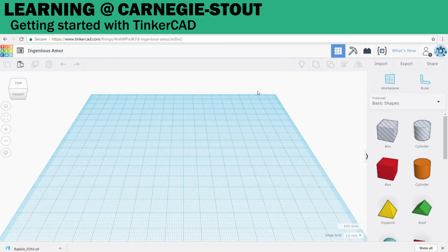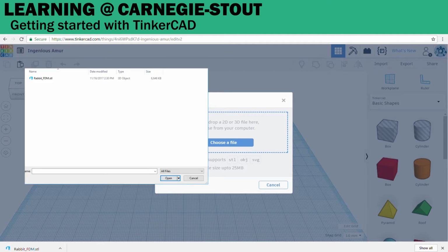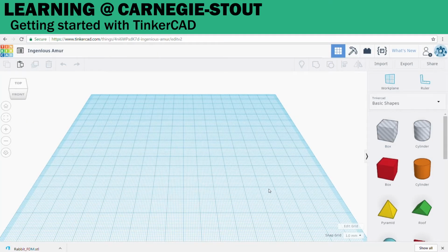Another great thing about Tinkercad is it has the import ability. You can import a model that you find on Thingiverse or many other sites. Click on the import button and choose File. Once you select your model, click Import and wait for it to load.